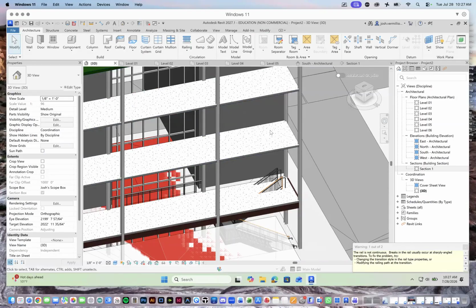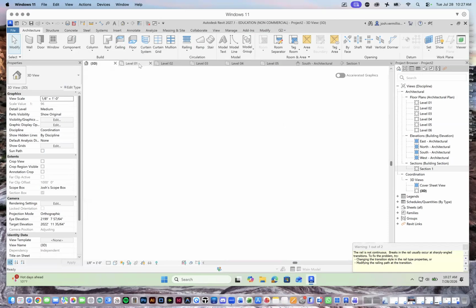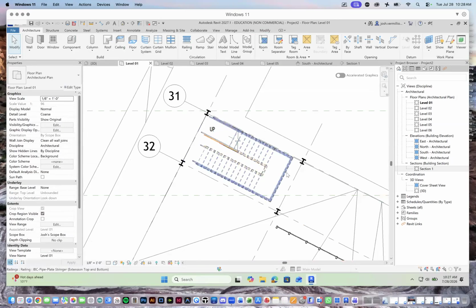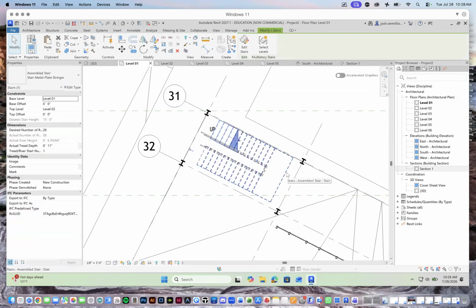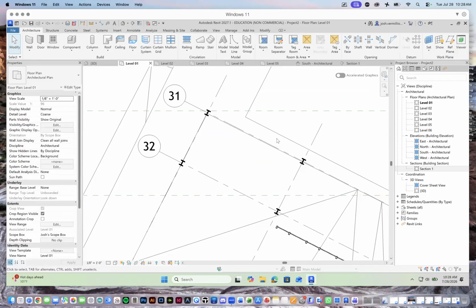All right. And each time it's going to look at those level to level and floor to floor heights and then begin to use the same rules. All right. So that's what's kind of nice about this, that you can see that I have stairs, railings, landings all put in. It's all to code. That's always a good thing. Let's go to Level 1. And what I'm going to do is take all these stairs and delete them again. All right. Let me just redraw this.